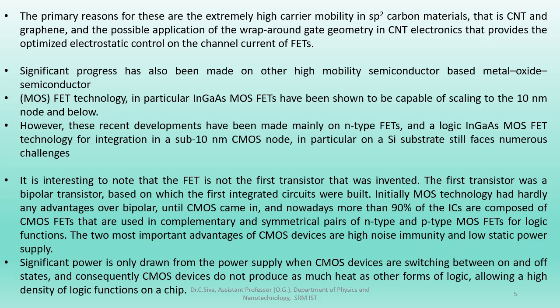Why CNTs are promising, again: CNTs are attractive due to the sp2 carbon bonding. CNTs can also use wrap around gate structures, giving excellent electrostatic control.